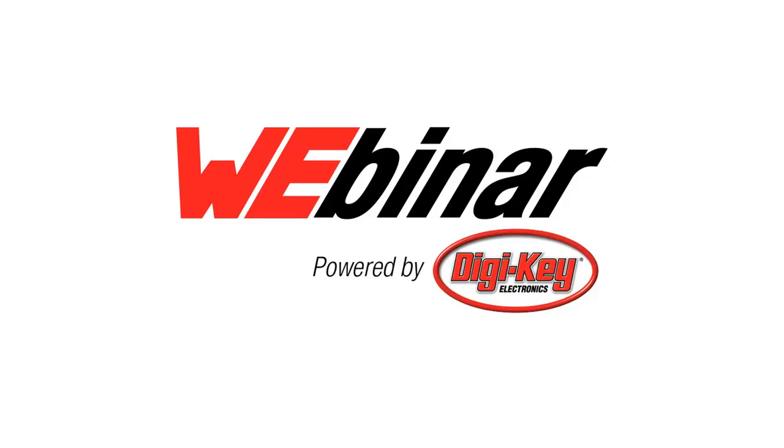Our next question: what is the difference between USB-C source and USB-C sink? Sure. USB-C source is the device that is driving VBUS, putting a voltage on it and providing the power. A sink device is accepting the power. That's your phone if you're charging it, or some other small IoT device that has a battery, for example, and is accepting the power. That's the sink side.